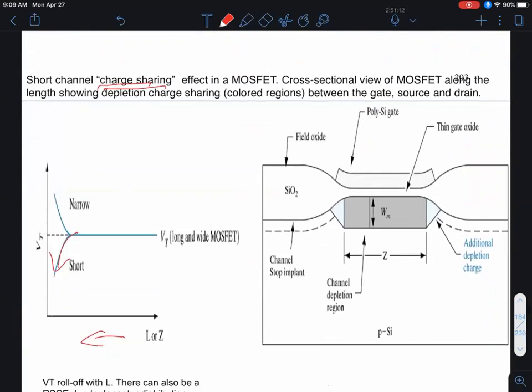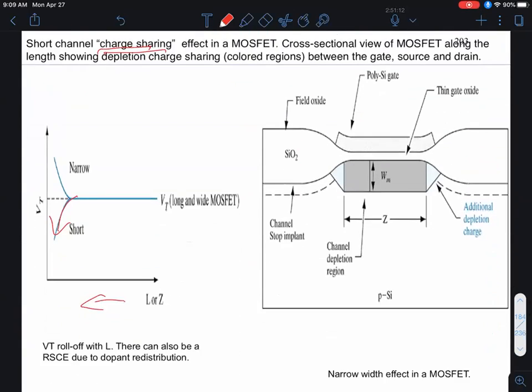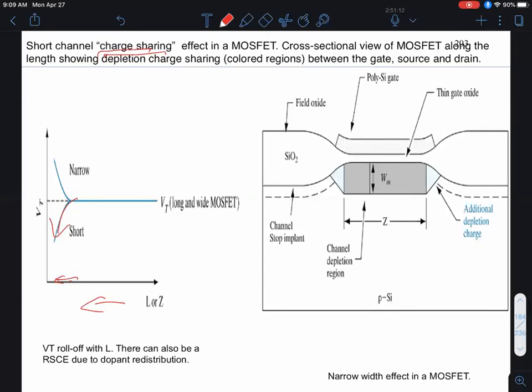Now that turns out to be a problem in manufacturing, because in CMOS technology, you're always pushing the limits in terms of having as short a channel length as possible. Because you've seen, if you have a short channel length, according to the Dennard scaling rules, you can put a whole bunch of transistors together on your chip. The transit time between the source and the drain is shorter, so you get faster transistors. It consumes lower power per transistor switching operation. Lots of good things happen, okay? The problem becomes, in manufacturing, you can never control the channel length precisely. And if you have variations of the channel length, that also corresponds to variations of the threshold voltage and other circuit parameters.